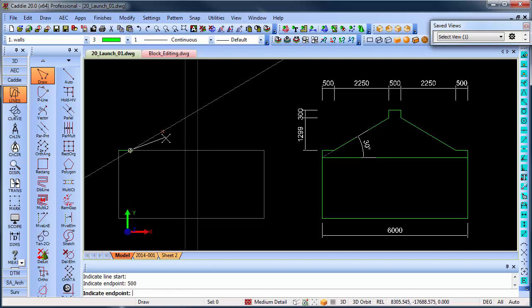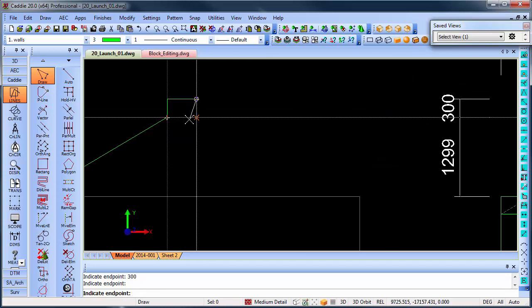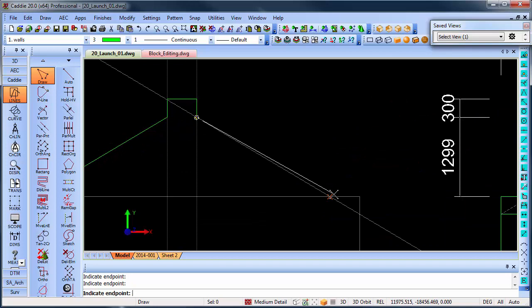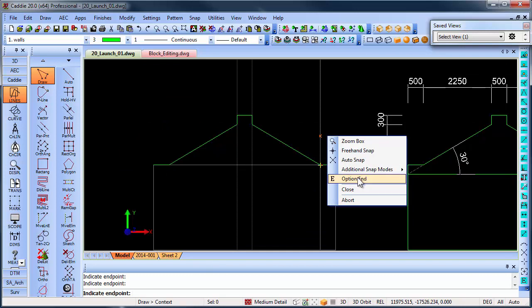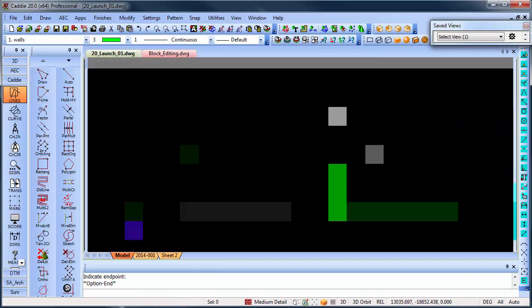Now you will see it projects 90 degrees and 30 degrees. So if I just hover my mouse over the 30-degree angle, I can go there. Once again, go up 300, go across to that point, go down where I can now project that point, go down 30 degrees, and then back to that point over there. So that is all achieved just by using the polar tracking.